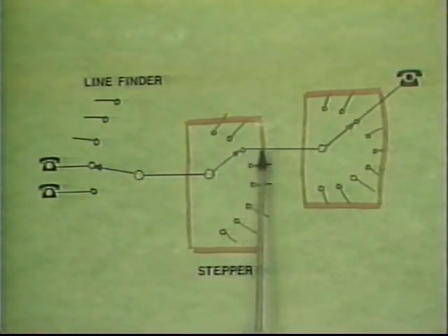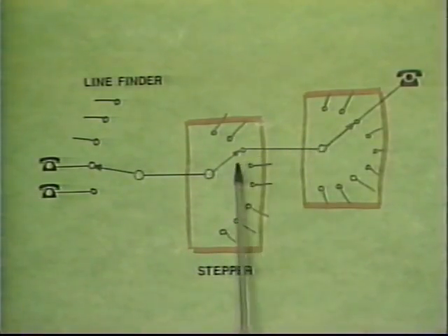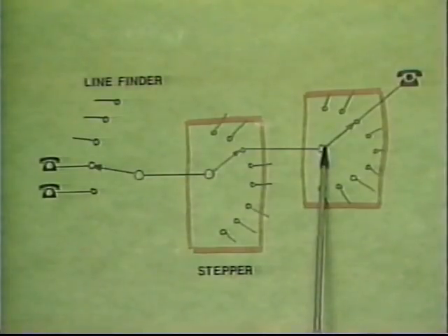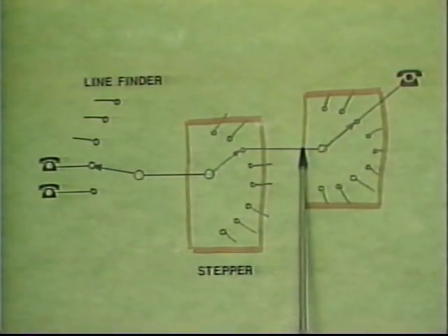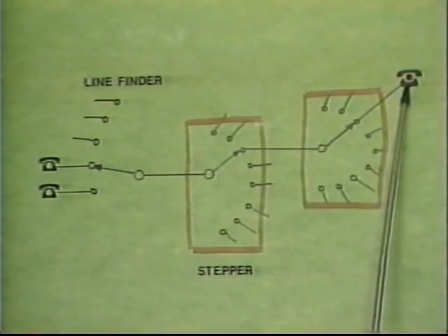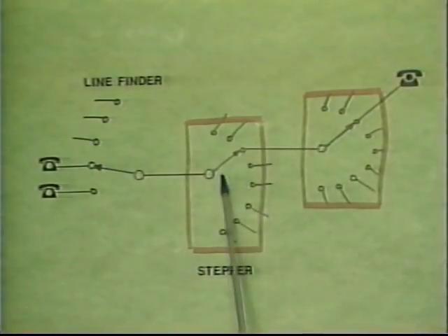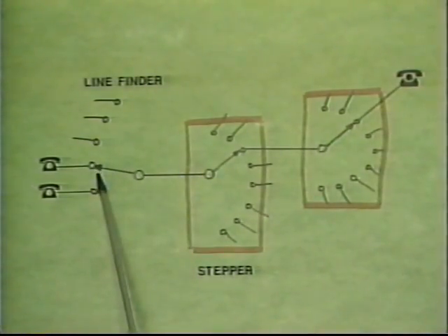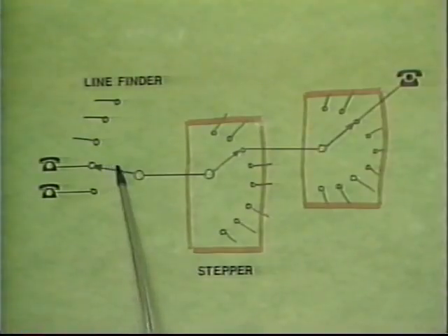Also, as the digits were dialed through the levels of the system, each of the switches was locked up, completing the connected call. This meant that only one call could be placed through each of the stepper switches. To overcome the problem, telephone companies designed parallel stepper switches which allowed multiple calls to take place. Eventually, though, the volume of calls made the stepper switch an unwieldy device or design in telephone networks.